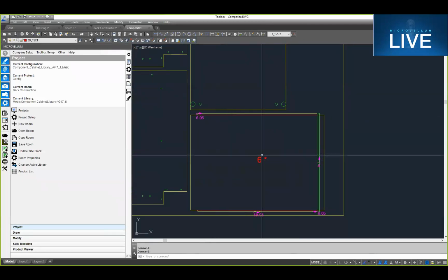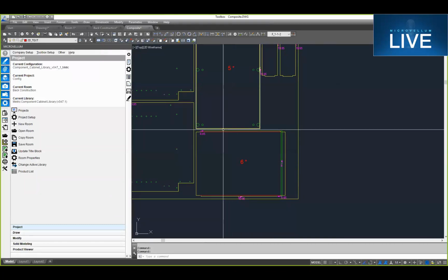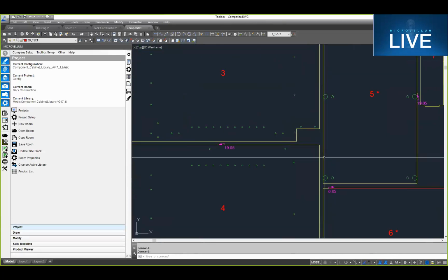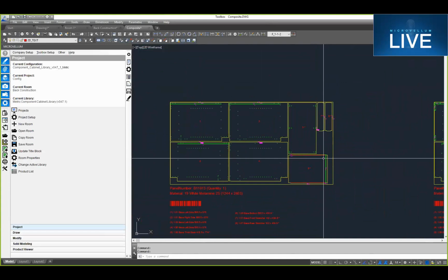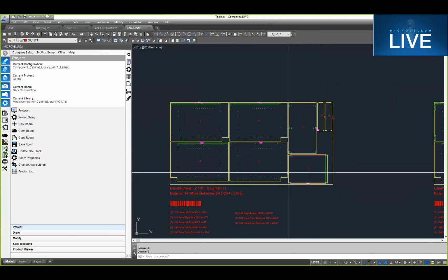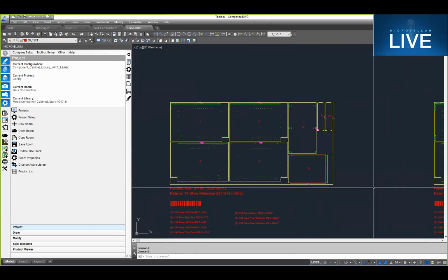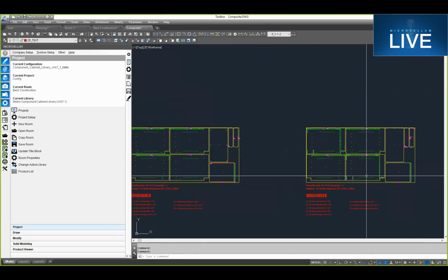And so just some different things to think about as you're preparing or looking at different construction methods, how you would want to handle that. We do have the ability to run phase 6 first as well. So if you are using Dado construction, there are situations where you're going to have machining on both sides of a part, and so those can be handled as individual part programs like this, or we can send the entire sheet out, machine those things with a couple of trims on it first, and then flip the whole sheet over, batch all that together, so you do that machining and part handling as simply as possible.